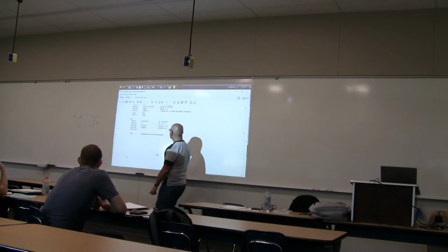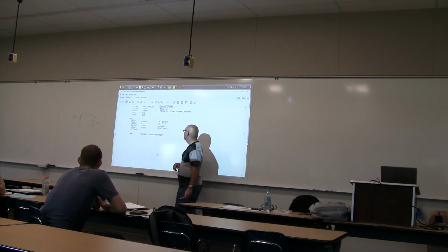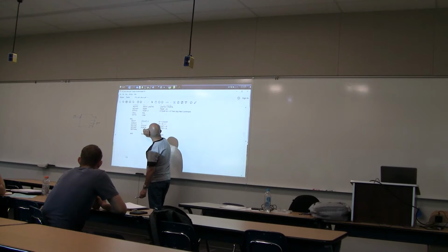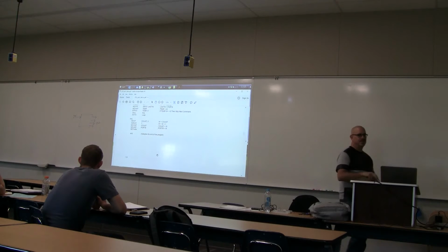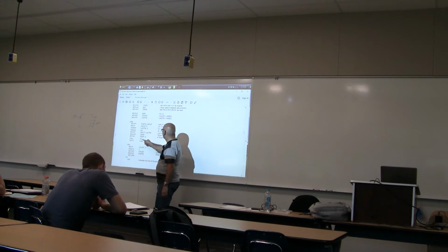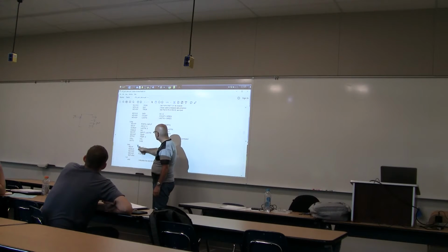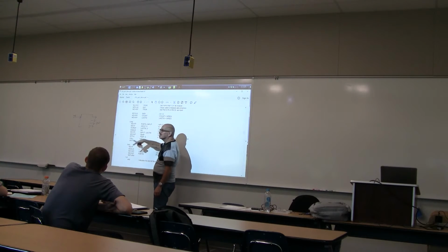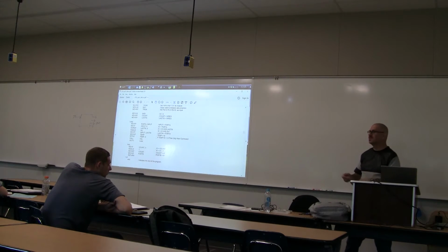And increment L basically adds 1 to the count and sends it to those output pins. Right, so this increments the count, this moves it to the output pins, and then return says go back to where we were called from, which brings it back up to here, and it goes back to the top of the loop and continues. So most of the time it's sitting here, when the input changes, it comes down here, does this, goes back and continues. And you're going to load this into the simulator and step through it in software, and you'll see that behavior.